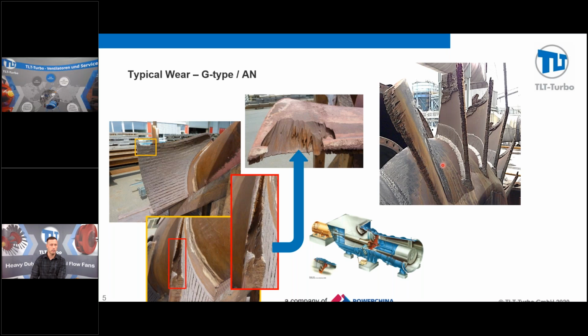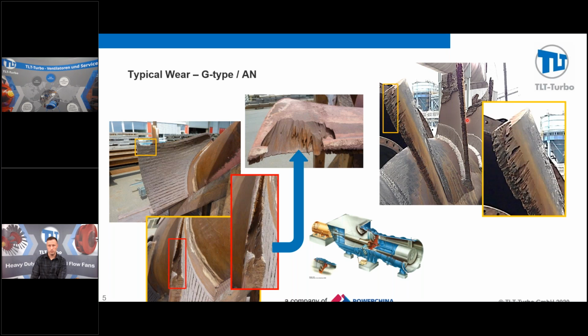Now, the mixed flow fans are very susceptible to imbalance. If you lose a large chunk here, it'll throw the mass of the rotor out, which will cause a heavy imbalance in the fan system. As you can see in a zoomed in picture of this edge, it's channeling on the outside on both sides, but also channeling all the way up the middle of the blade, which is causing the air pressure and the airflow and the media to travel into here, but it has to exit. So it's exiting out the tip and it's starting to work its way through the top of the meat of the blade. And that's where you see the large erosion up here on some of the fan blades.